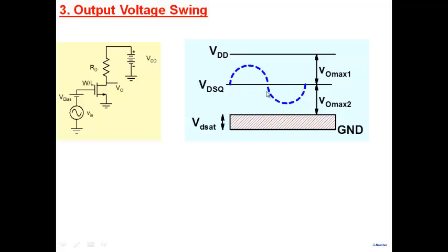And note that as the net drain to source voltage decreases here, what you have to do is ensure that the net drain to source voltage is always larger than VDSAT, which is shown over here. All right, so you have to ensure that this minimum point doesn't go into this forbidden region here. At the most, it can touch this particular point. And from this extreme, it's obvious that the maximum cannot go beyond VDD here.